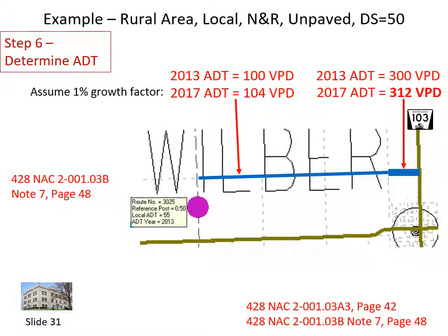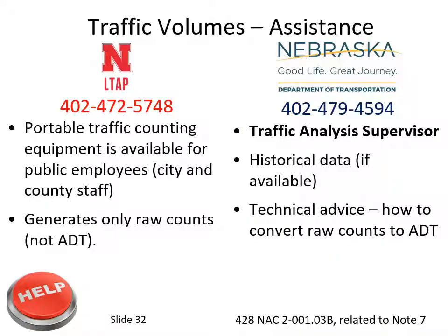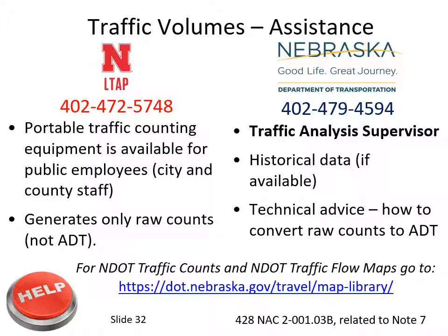There is nothing magic about the 1% growth assumption. You need to know the trends in your area. The Nebraska DOT can provide some guidance. This screen shows assistance that is available from Nebraska LTAP for portable traffic counting equipment and from the Nebraska DOT for technical guidance. This help is available only for counties, municipalities, and their consultants. Statewide traffic counts and traffic flow maps can be found on the Nebraska DOT's map library online at the link